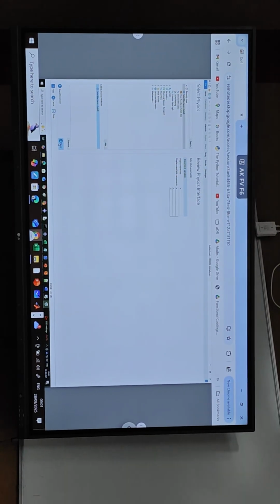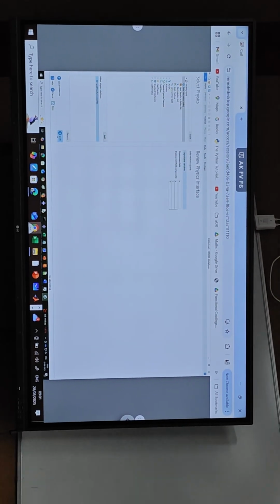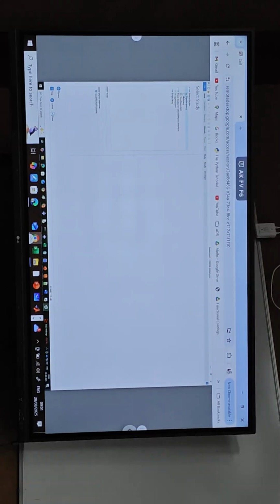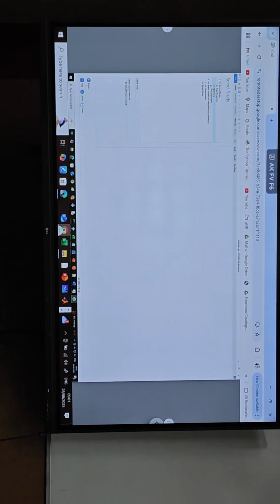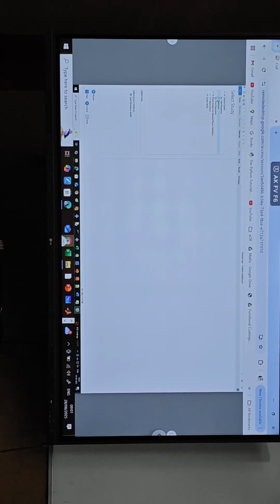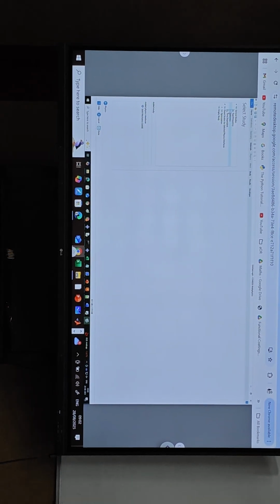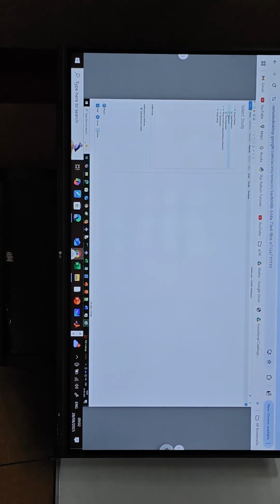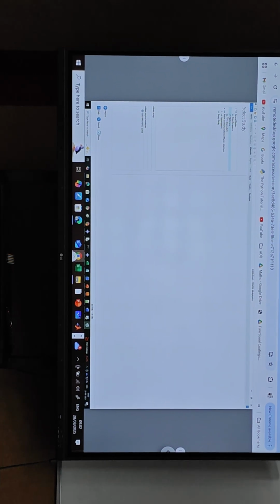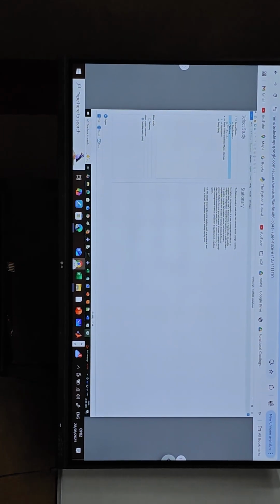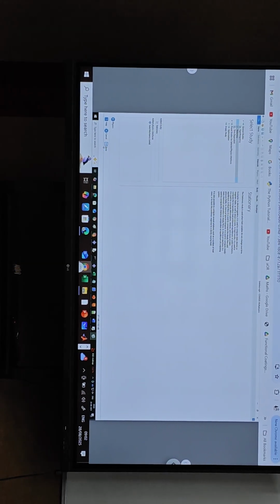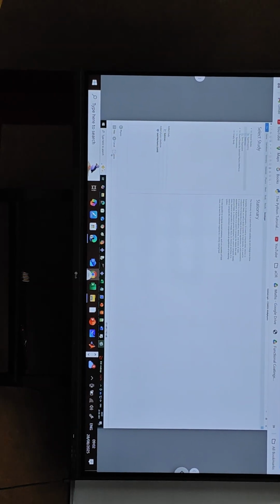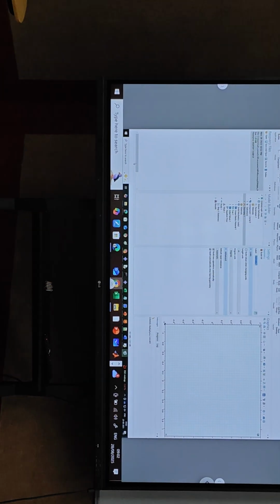You can go to the study button. Once you click the study button, you will have stationary. Please don't talk when I'm bringing it. So you have these studies. You can choose either the eigenfrequency analysis, stationary or time dependent. For today, we're just doing a stationary analysis. There is no need for the other two. So we click here, done. And once we do this, the physics and the study are added into the interface. You will notice it here.